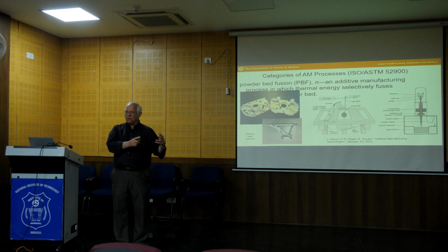And we like amorphous polymers for that process because we're melting and flowing, and we'd like to have a range of temperatures where the material has varying viscosity, because we don't want it to be too viscous or it doesn't flow. If it's too liquidy, then it doesn't stick where we want it to.